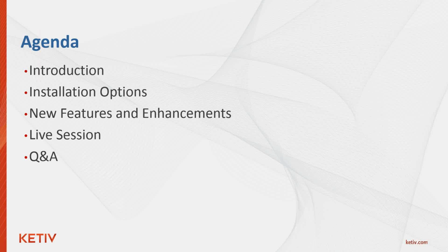So before I actually jump into my PowerPoint presentation, which explains in detail the new features and enhancements of the Revit 2016 R2 update, let's talk a little bit about how you can find and install the R2 update for yourselves. So this is a subscription release, so everybody on subscription has access to this. If you are on subscription and already have Revit 2016 installed, you can simply access the Autodesk Application Manager, click on the Update Software button, and then locate the Revit 2016 R2 update and install it, and you should be good to go. And if you can't find the R2 update on the Application Manager, you could always go to your Autodesk Manage account if you are on subscription and click on the Products and Services button, and then click on the Product Updates and install it that way.